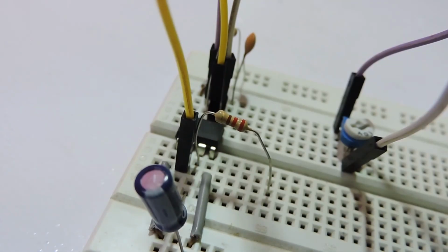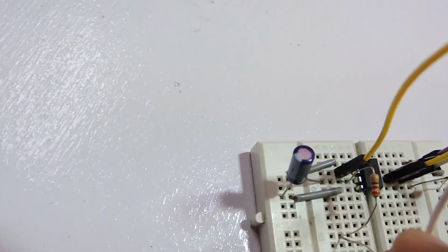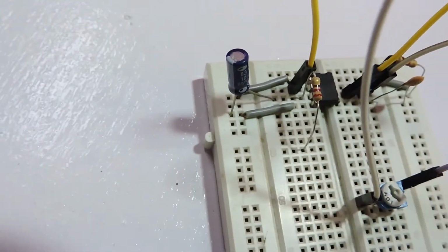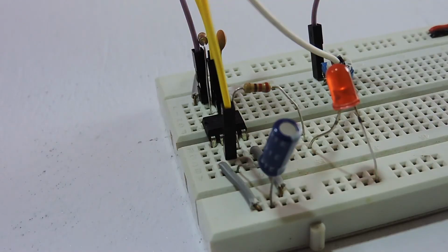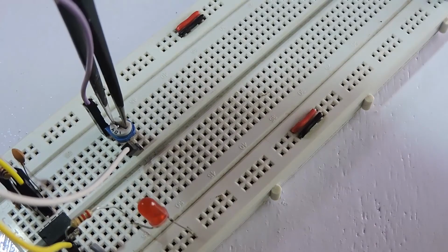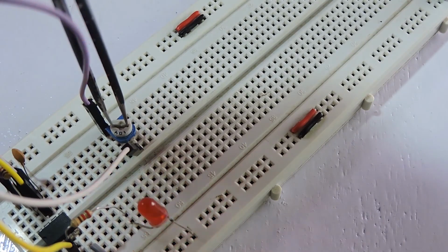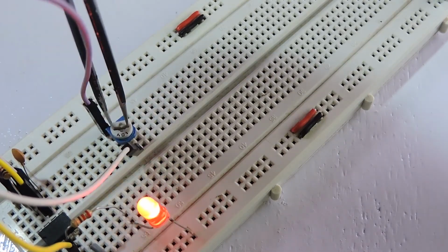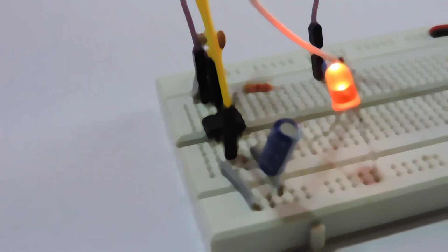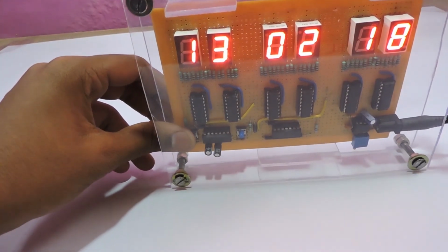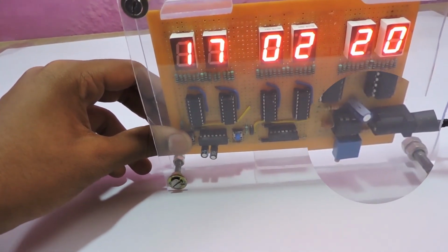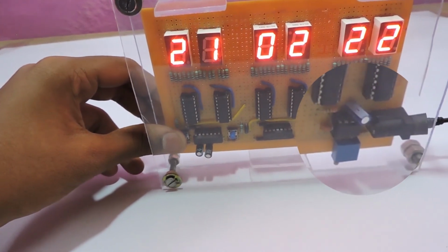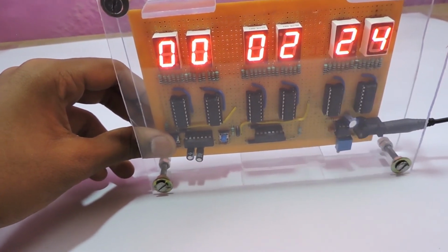Once you finish the circuit, you need to connect an LED with a 220 ohm resistor at pin 3, which shows the output of the circuit. Once done, we can see the LED blink. We can even change the frequency of the clock by changing the value of the variable resistor. But for some of you, it's so lame and you may be confused where to use it. Why not check out how to use this clock and make a digital clock by clicking on the cards on the right hand upper corner of the screen.